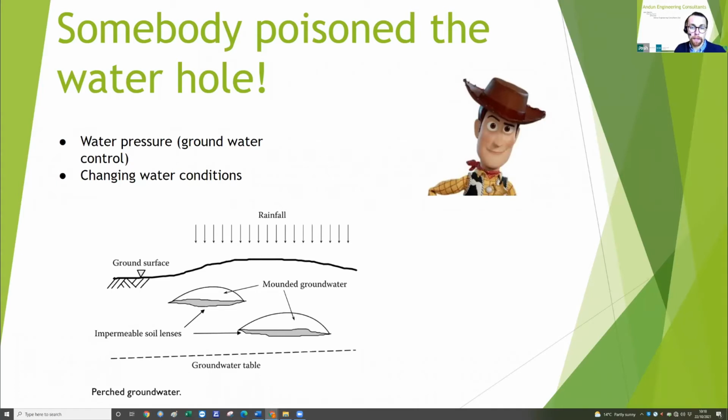The creation of a retaining structure in an area of high groundwater is normally associated with a change in groundwater conditions. So, for example, if you've got a basement and the excavation needs to be kept reasonably dry during construction, this is often done by pumping from sumps in the excavation. But this has an effect of lowering the groundwater table inside the excavation, thus promoting flow through. So it's important to keep that in mind, because that flow through can lead to localized instability of the soil, where the hydraulic gradients are the highest.